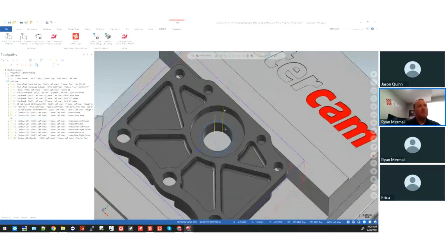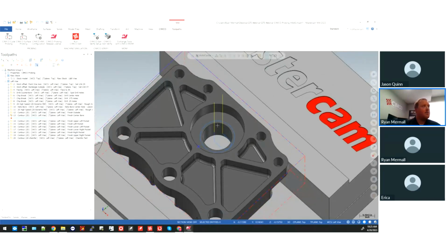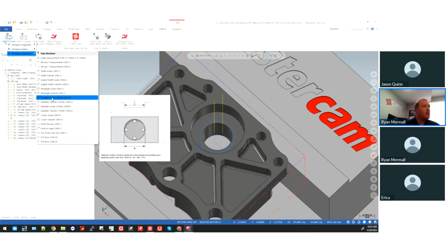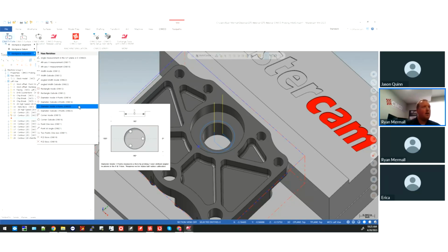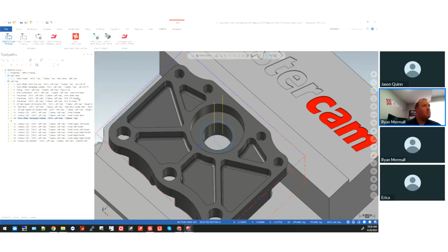So for instance, if I had like a center bore cycle within there, we'd have that actually as a finish contour, using like a wear compensation in this case. What I would be able to do is actually go into like a workpiece inspection category, determine, okay, do I want to set that up in a 4-point or 3-point method? 3-point will actually allow you to define the specific vector angles that you'd want to do. Would be good for like these half moon shapes down at the bottom of the part there. But in this particular case, I'll do like a 4-point method.